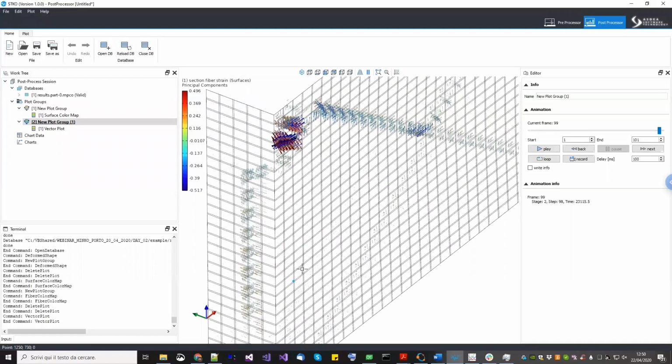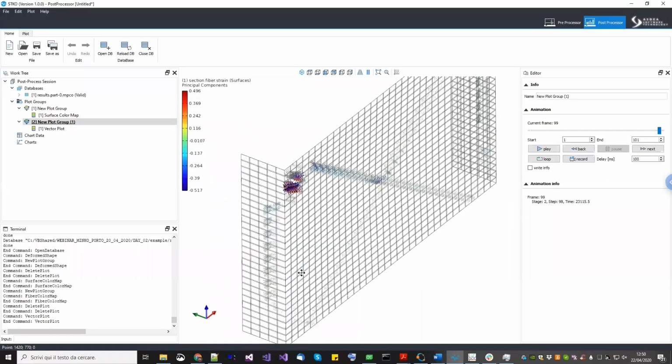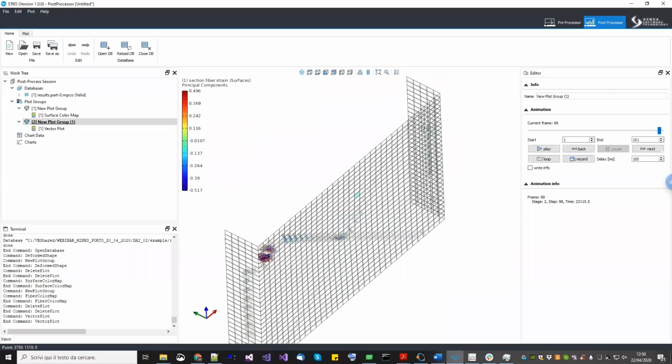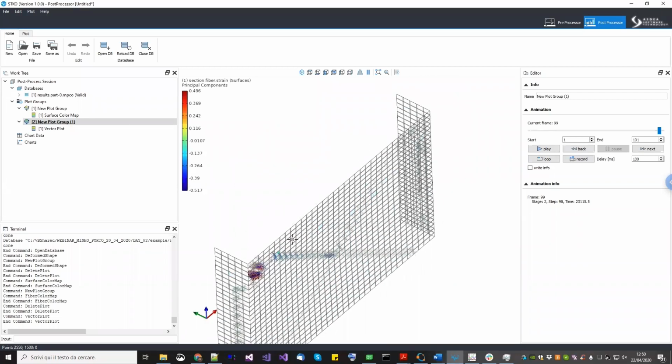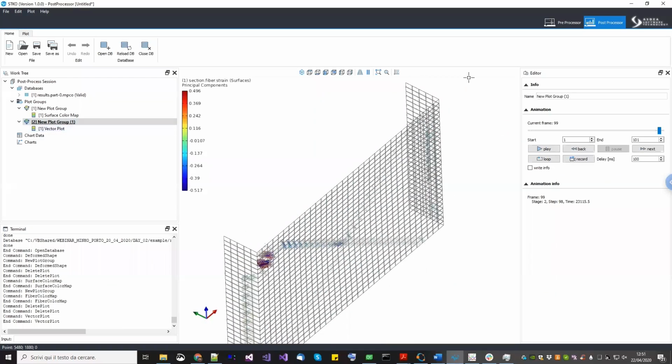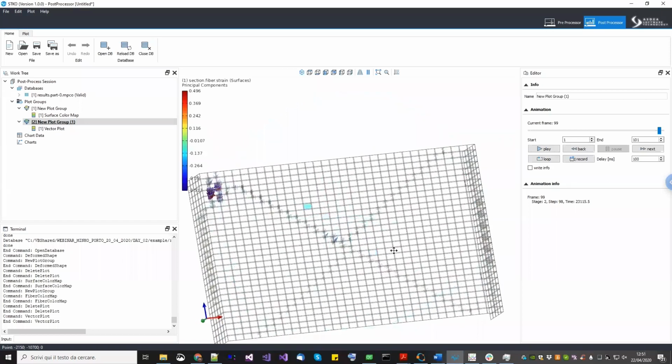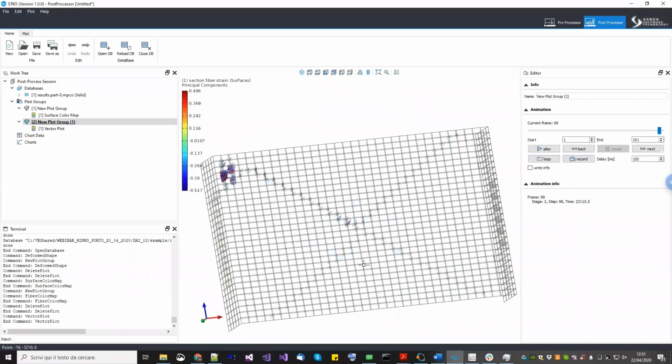Okay. That's why at the beginning I was saying you have to take care about what kind of shell element you use. Because for example, in this example, if I use the thin shell instead, I will not obtain the same results, even if the wall seems to be thin, okay? And I will give you an example of what is happening. Oh, and take care that in this example, the bricks are not failing, only the mortar joints, okay?